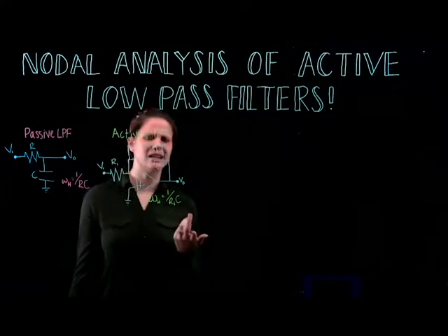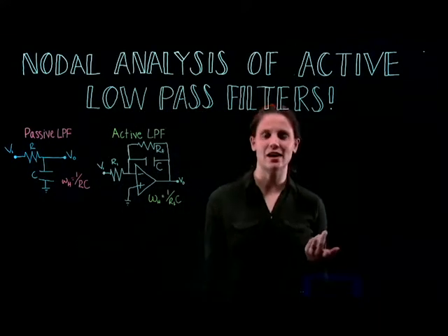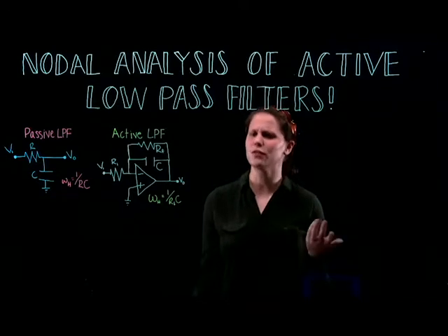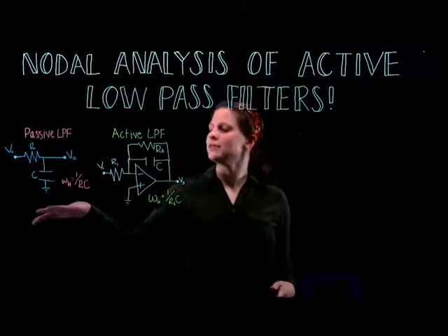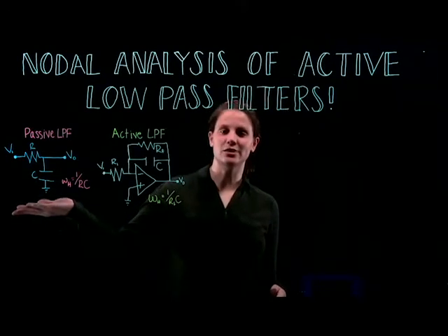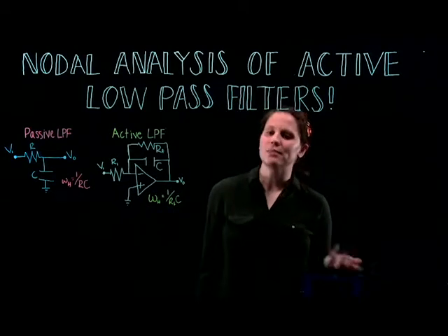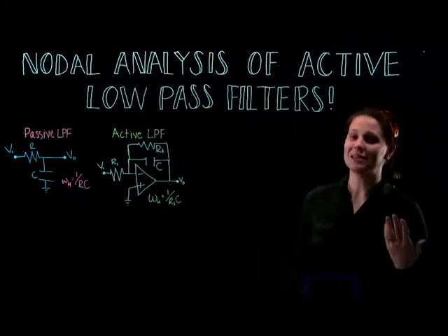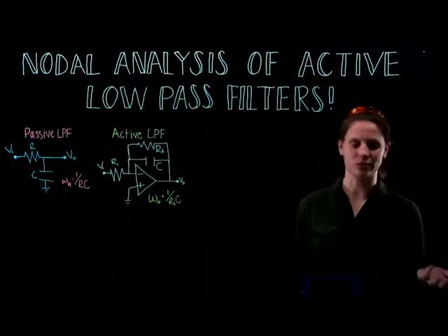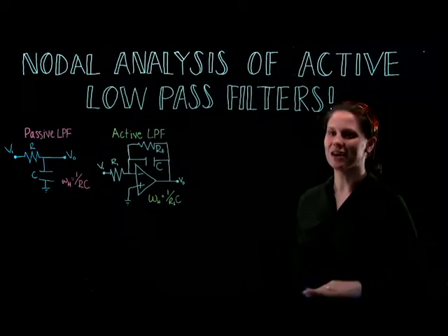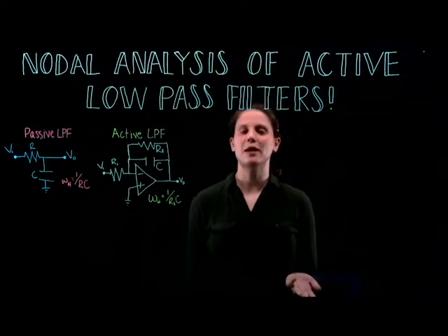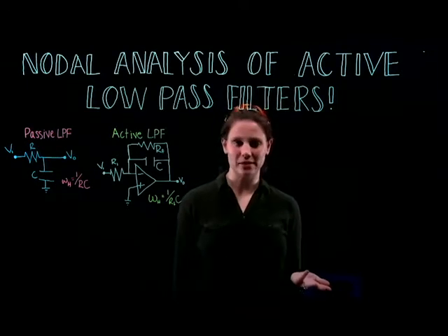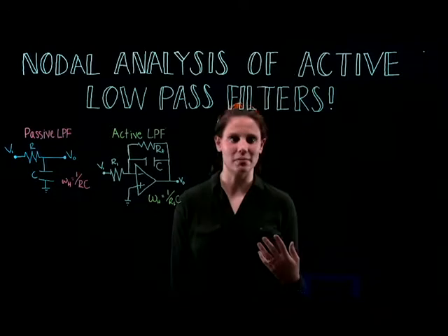First, I wanted to talk a little bit about the significance of active low-pass filters over passive low-pass filters. Passive low-pass filters we're familiar with. This is the structure of them right there. Something that we run into with low-pass filters is that they result in attenuation, even though they effectively filter noise. Attenuation is a reduction of the output signal. Since biomedical signals are already low in amplitude, the passive low-pass filter isn't a great bet.